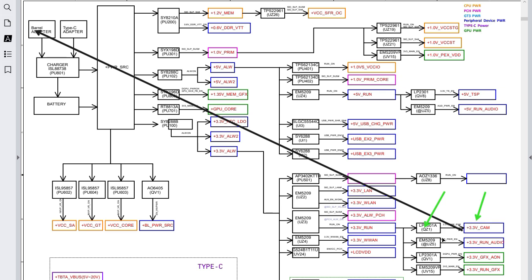So we should go back and look for the source or the IC that feed this IC. This is the IC. This is the responsible here. Okay, this IC is the IC that is, of course, that control this IC. So we should check, for example, this one. We didn't get here plus 3.3 volt for this IC. Means this IC is bad? No, we should check the input. The input here should be 3.3 volts.